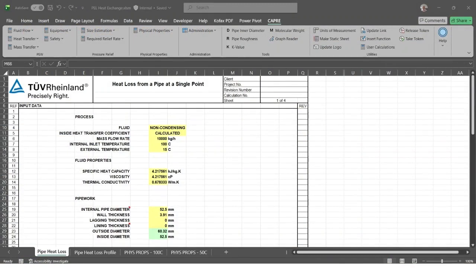And today we're going to look at heat loss from pipes. So we've got some hot fluid inside our pipe. Obviously it's going to lose some energy to the outside world, ambient heat transfer, and we need to understand how we calculate that. And then we can think about whether it's worth buying lagging or if we're going to do trace heating, what heat load might leave heat tracing, additional steam, whatever it might be. We can understand that heat loss and then act accordingly.